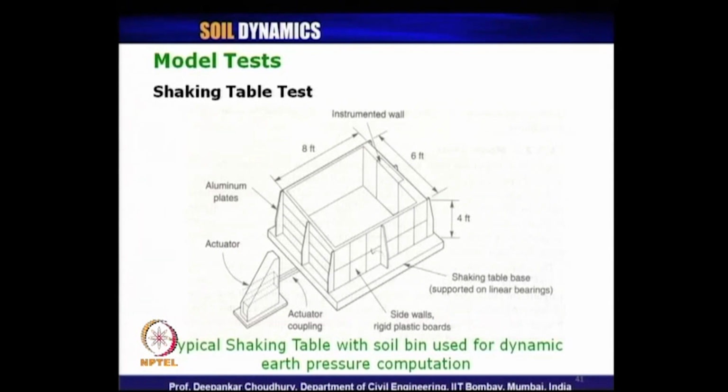Why? Because in structural engineering it is pretty common to do 1 gravity or 1G model tests, that is, you scale down your 10-storied actual building to a small model 10-storied building and do the test. You will get fairly accurate values of stresses, displacement and so on from the model test. You apply the scaling laws, etc.